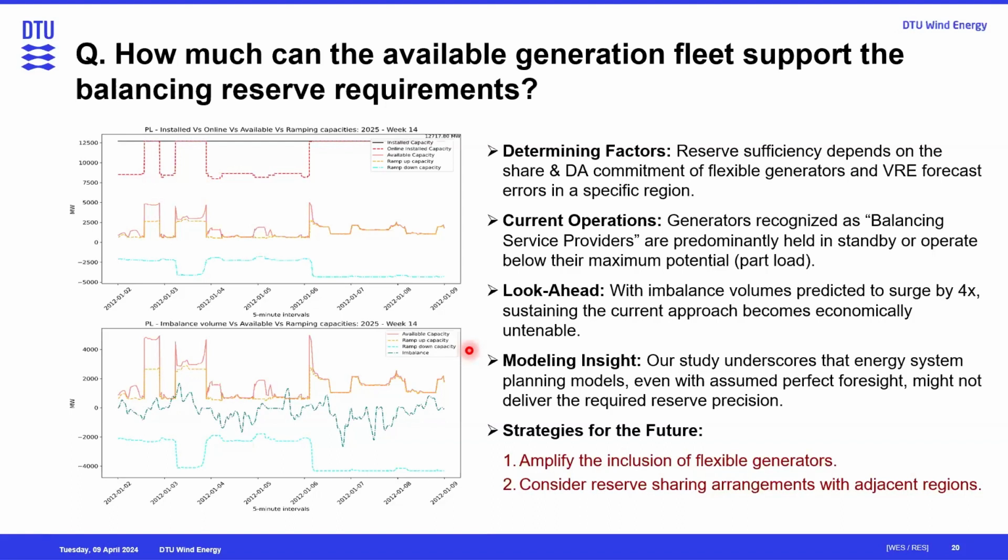More than the available ramp up capacity. What does that mean? During that period, either you get it from your neighbors or you have to live with your automatic reserve, right? If your automatic reserves are utilized during that time, and if a fault happens, then you are moving to an even worse situation of a blackout.